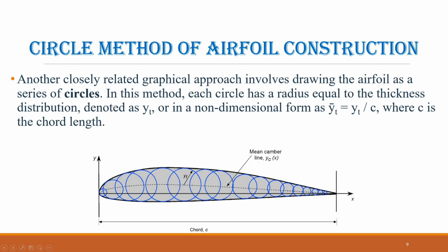This graphical technique provides a simple and intuitive way to visualize how an airfoil shape is generated, showing how thickness and camber combine to form the complete profile. It is particularly useful for teaching purposes or for gaining an intuitive understanding of airfoil geometry. However, while the method is excellent for visualization, it is generally preferable to construct the airfoil surfaces numerically, calculate precise coordinates, and tabulate the data points as described earlier.